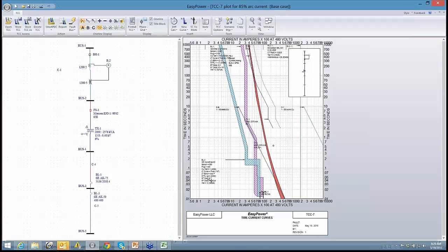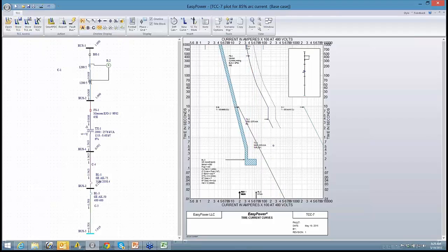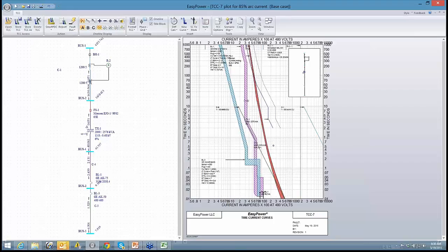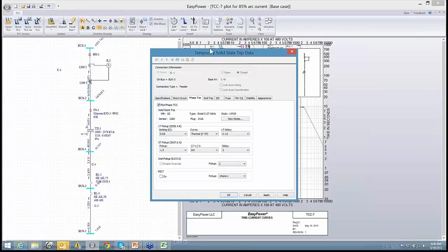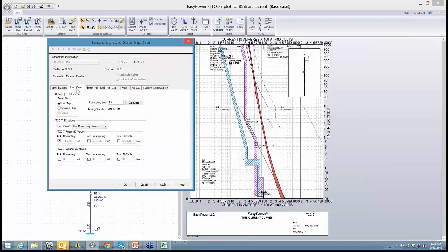And then if we reference everything from BL3, we can see that we have the potential for doing, again, fault the downstream bus. Insert the tick mark, and I'll fault it again, and then go through the whole procedure with the upstream breakers.